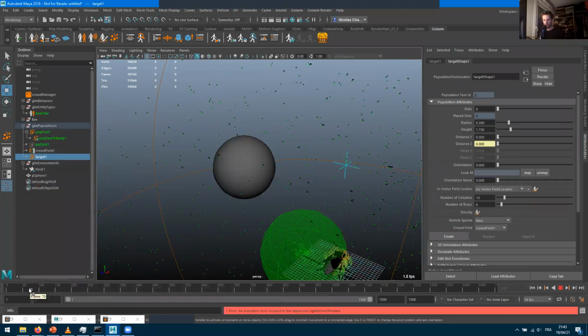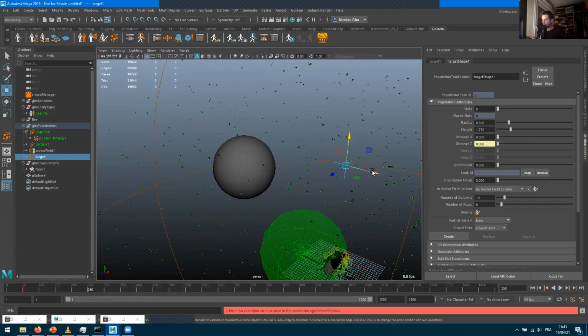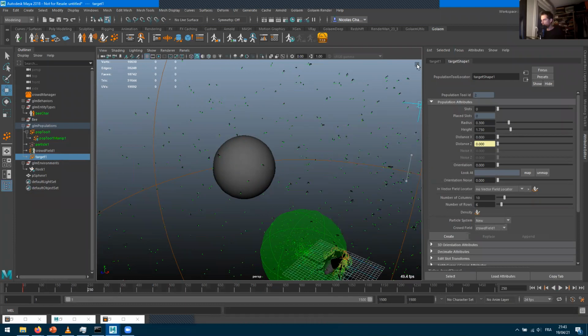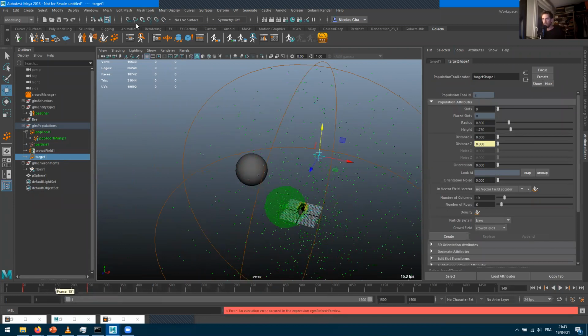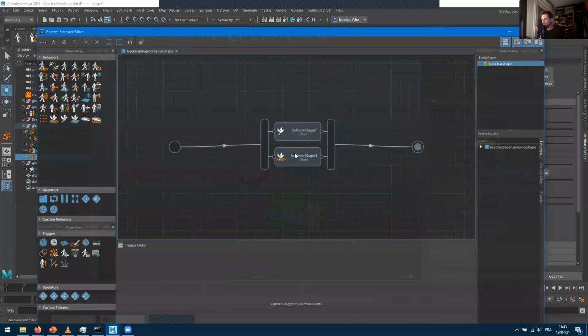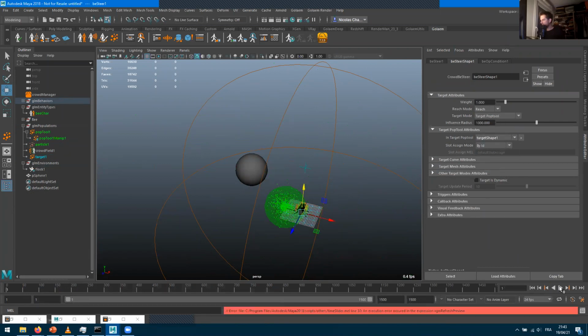I'm going to do my best to keyframe animate it. So okay, frame 50, frame 200. Put it something like here. Okay. So now I've keyframed my locator. That's great. And I just have to change my steer behavior to reach. I want to reach a target pop tool, and the pop tool I want to reach is that one here.